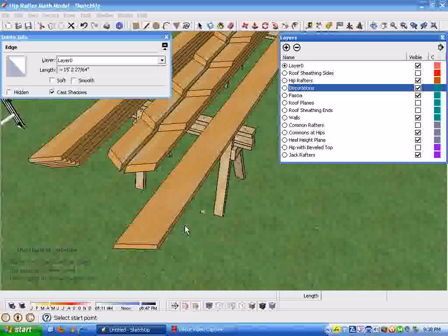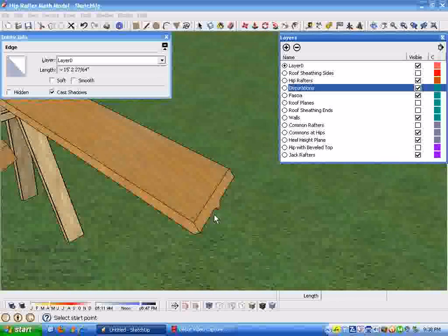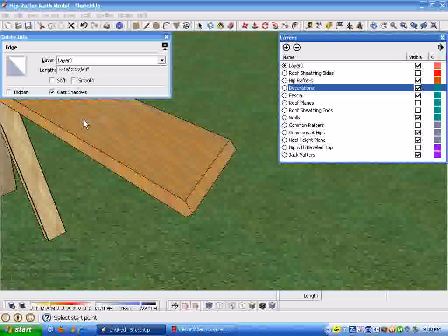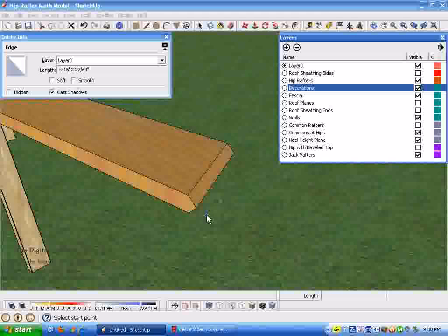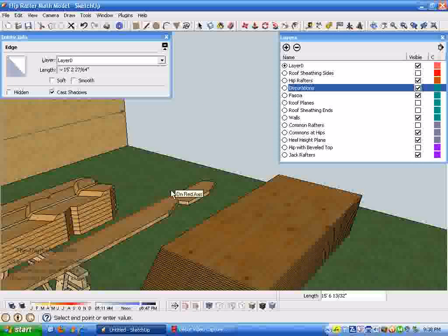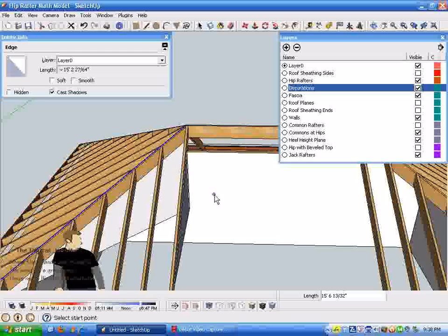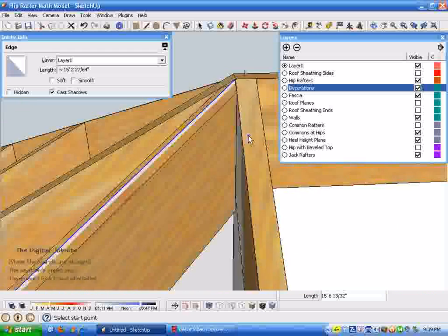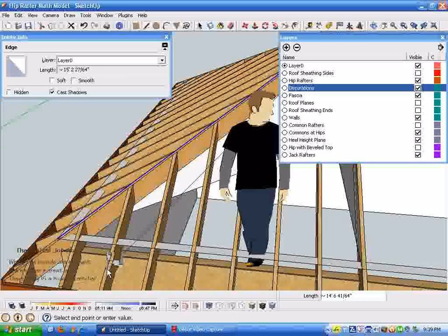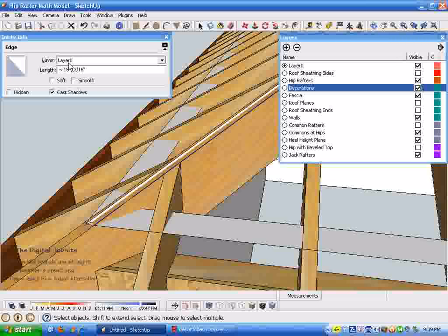When this rafter is laid out, every carpenter is going to do this a little bit differently, but when I'm laying out a hip rafter to cut, I like to put these 2 bevels at the top. I lay a framing square with 16.97 and 7 inches on the 2 blades of the square, come up with this angle, and cut these 2 45s. Then what I like to do is measure from this point down to where the bird's mouth is going to be. That's not the measurement you get when you use a construction calculator. You get this other measurement represented by the blue line. So in this case, I can just click this point here and then click again down here, and I get the length by clicking that line. 15 foot 13/16 of an inch is the length I need to lay out on the rafter.